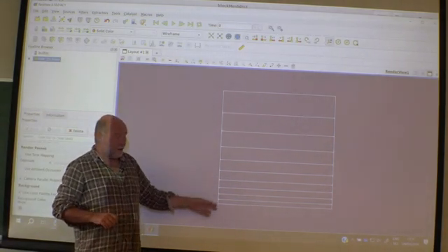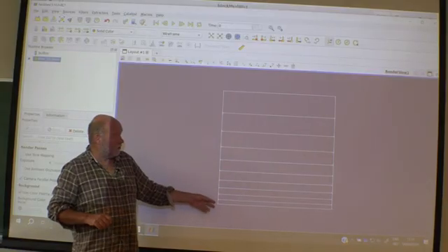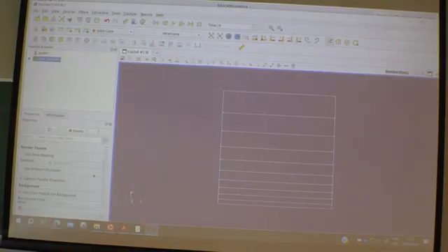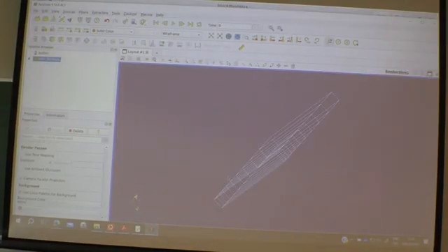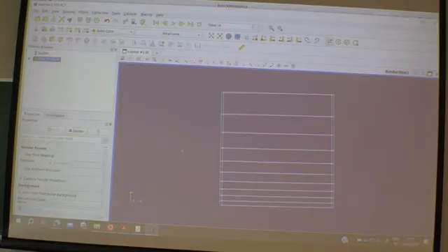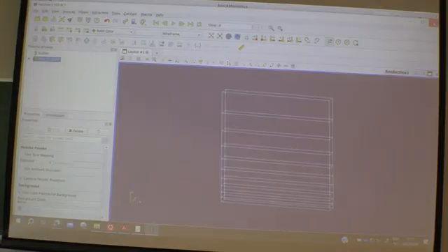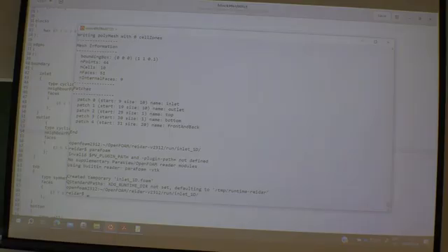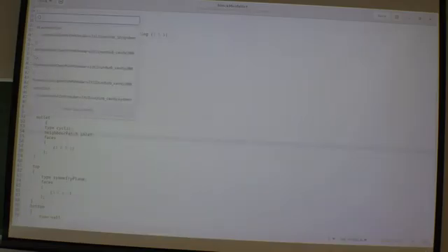So of course it's the boundary layer that is going to be important. We're going to use more cells later on, but never mind that. And yes, this one is now three-dimensional, of course, but we only are interested in the Y variation here. Okay, so far so good. Now we have to, sadly, go through the different zero folders.